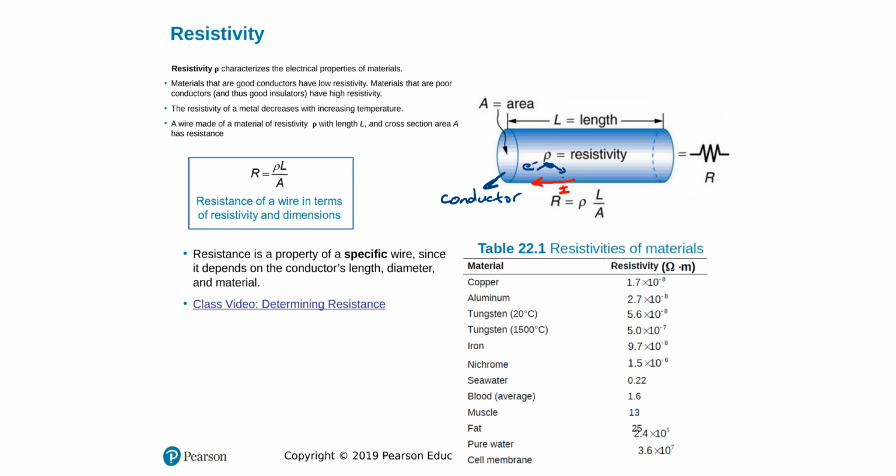That resistance depends on how thick our wire is, or cross-section area. We cannot touch base on that with a question. That depends on how long our conductor is. It also depends on the type of the conductor, how large are the atoms the electrons will be hitting, or how close they are to each other, and so on, which is defined as resistivity. So resistance of a certain wire can be defined, and we will use the R symbol for resistance, as equal to rho L over A.